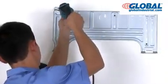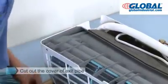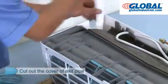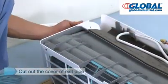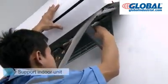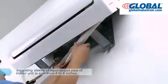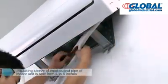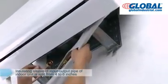Fix the mounting plate. According to the reserved position of the wall hole, confirm the direction of the exit pipe and cut out the cover of the exit pipe. Remove the drain pipe. The installation auxiliary bracket is threaded through the hole of the mounting plate to support the indoor unit. The insulating sleeve of the input-output pipe of the indoor unit is split 4 to 6 inches to facilitate the connection.